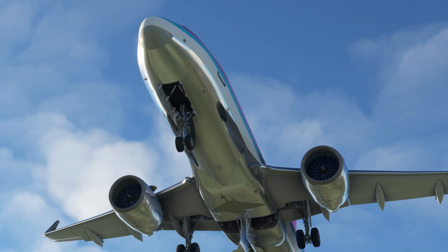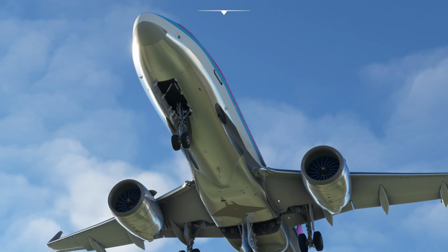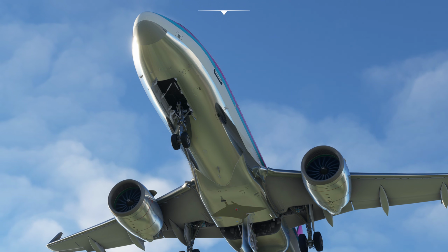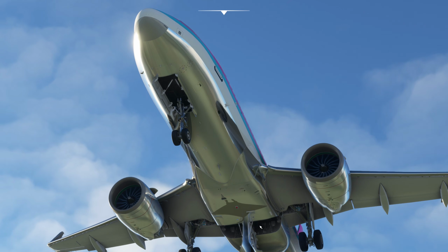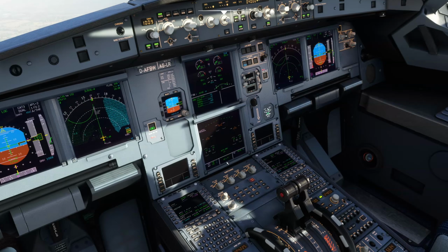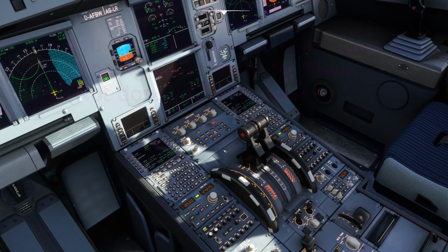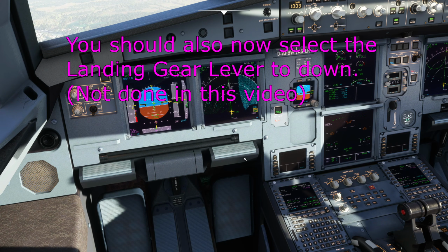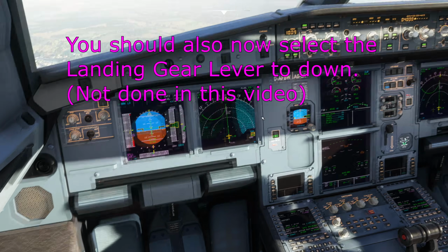So here we go. As I was talking about, huge drag. You've got big holes. So if you try to go around now and point this nose up into the air, this is getting into the airflow. And it's like having big speed brakes out. Let's fully configure them for landing. So flaps to 3 and flaps to full. Had no trouble slowing down in that case.